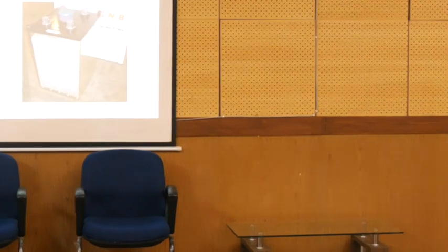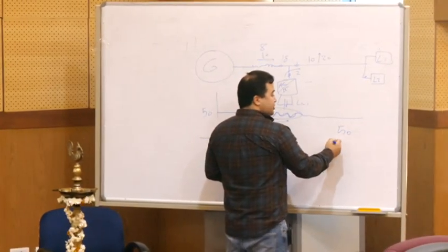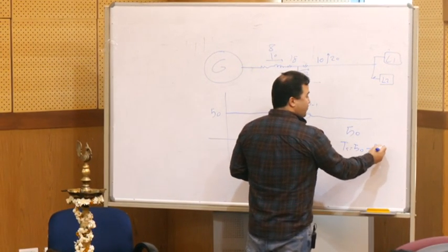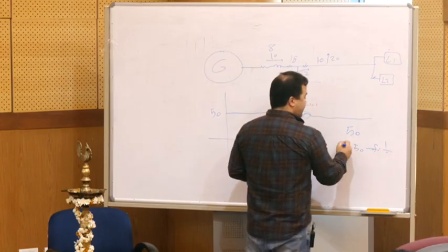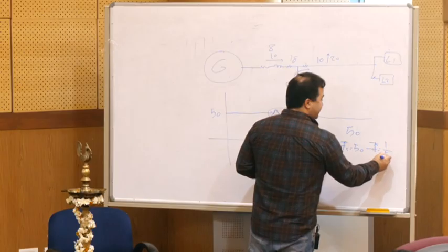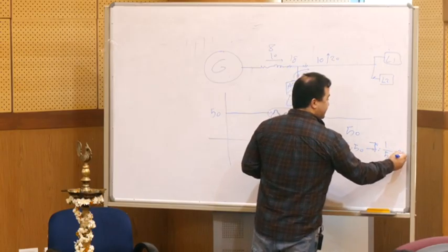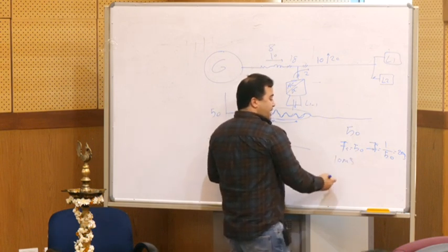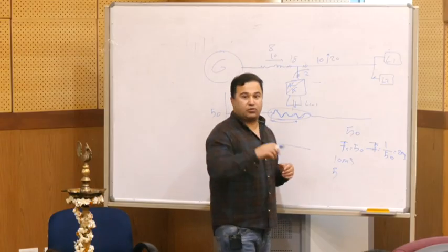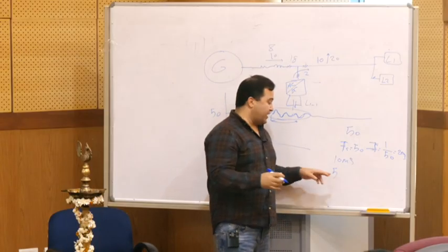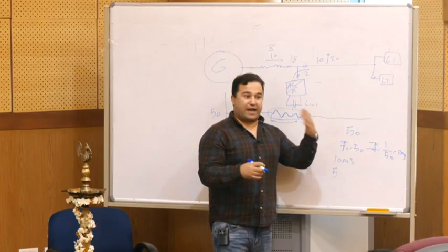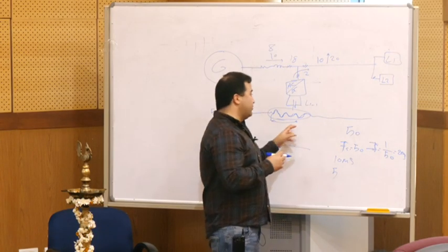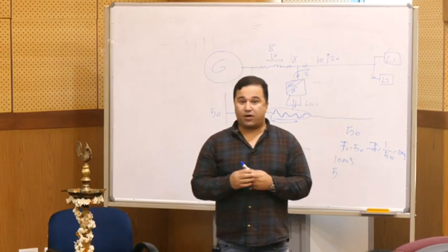If we consider the frequency 50 Hertz, F is 50, and T is 1 over F, so it's 20 milliseconds. So half a cycle is 10 milliseconds. And 5 milliseconds goes to the detection, so we have actually 5 milliseconds to react and compensate the transition. And this lithium-ion is not fast enough to compensate that part.